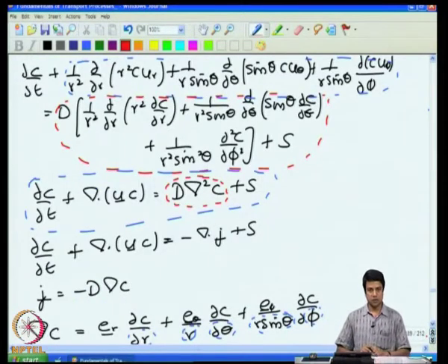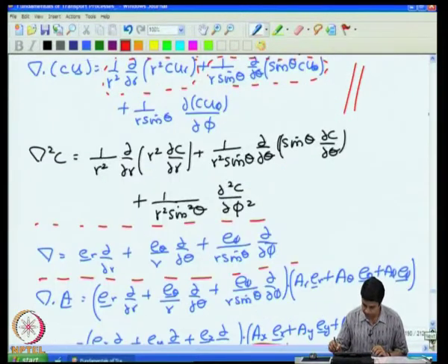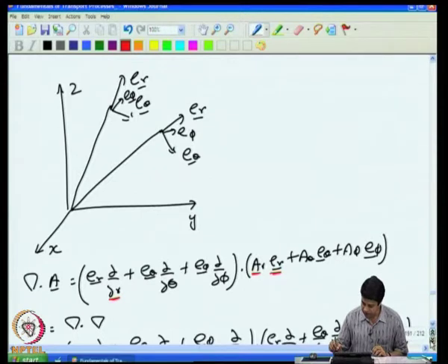So, once you write that correctly, you end up with the equation on top there, which contains the convective as well as the diffusive terms, and I showed you how to express that in the form of a convection diffusion equation, where we define the gradient operator as well as the Laplacian del square for the specific coordinate system that we consider. So, that gave us the differential equation.